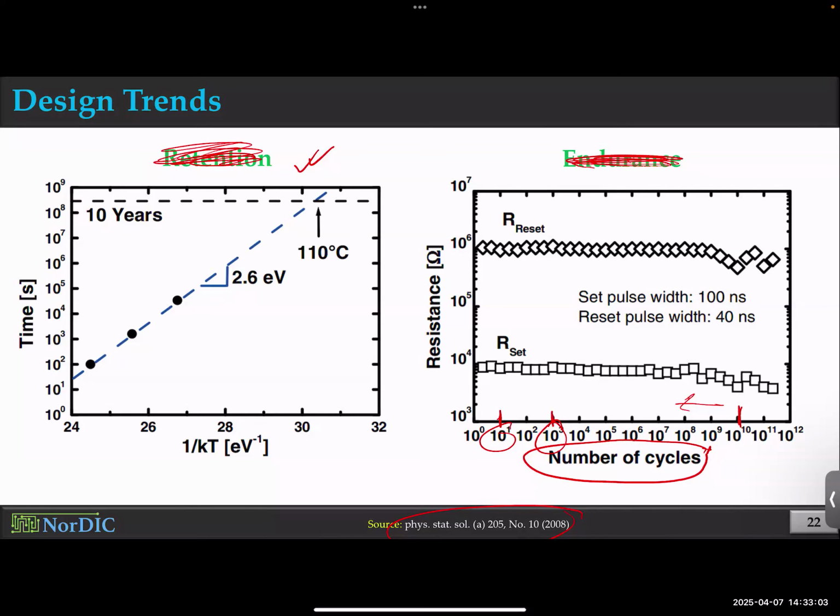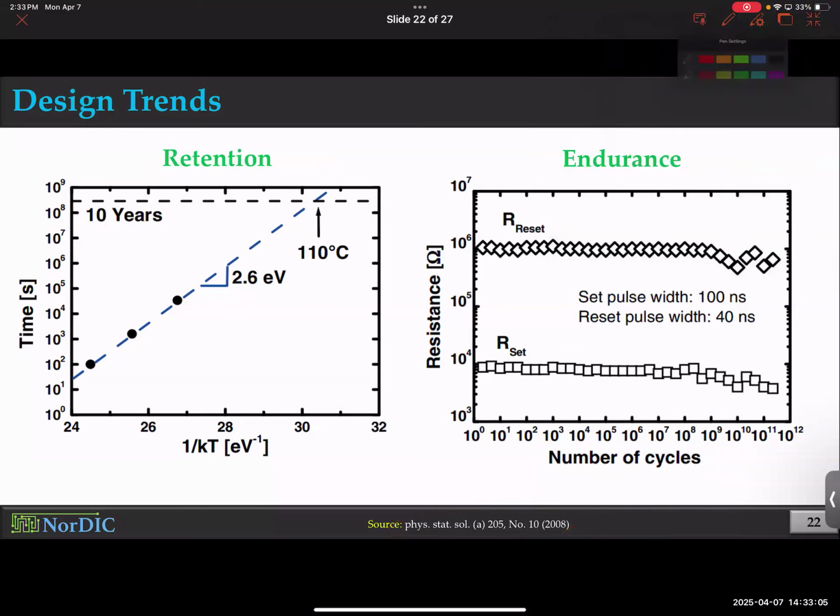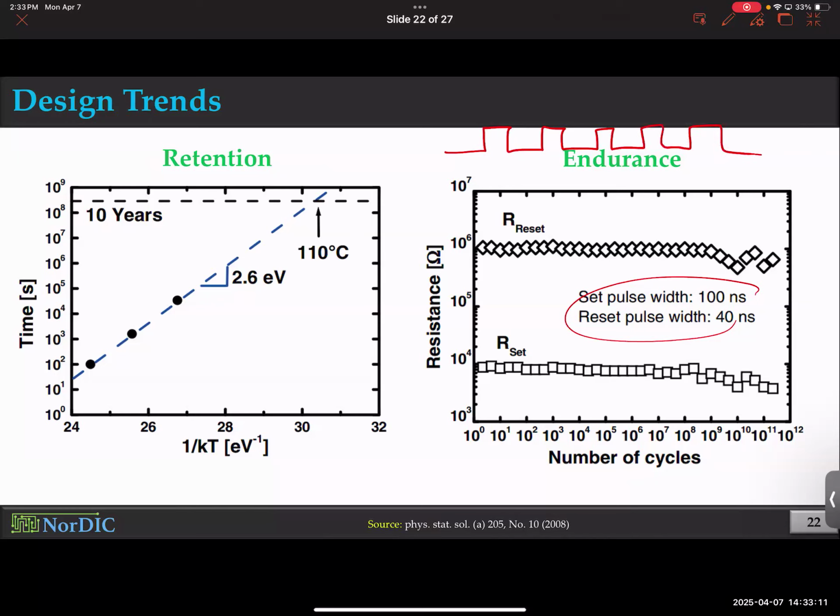Okay. All right. So notice the pulse width. So basically they're using a pulse like this. They're obviously not manually doing it, right? They set a pulse generator and it keeps writing the memory. And there is a semiconductor parameter analyzer that keeps taking results and generates a spreadsheet. And you just go there after a few weeks or so, take the data out and plot it and see how things are. Does that make sense? So what they're telling you is the pulse width is fixed.